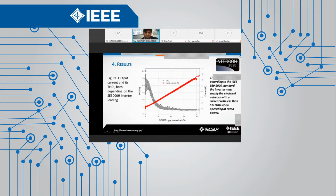In the other results, we can see that type of inverter. This type is the SolarEdge 3000, and how it works with the harmonics, total harmonic distortion, and the current. In the figure, we can see output currents and their THD, the total harmonic distortion of the currents, both depending on the inverter's loading. In this part, we can see how the current grows with the harmonics.